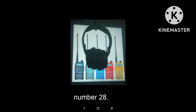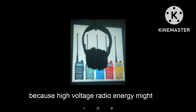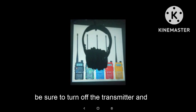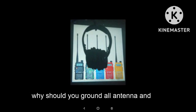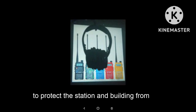Number 28. Why should you make sure that no one can touch an open wire feed line while you are transmitting with it? Because high voltage radio energy might burn the person. Number 29. What safety precautions should you take before beginning repairs on an antenna? Be sure to turn off the transmitter and disconnect the feed line. Number 30. Why should you ground all antenna and rotator cables when your amateur station is not in use? To protect the station and building from lightning damage.